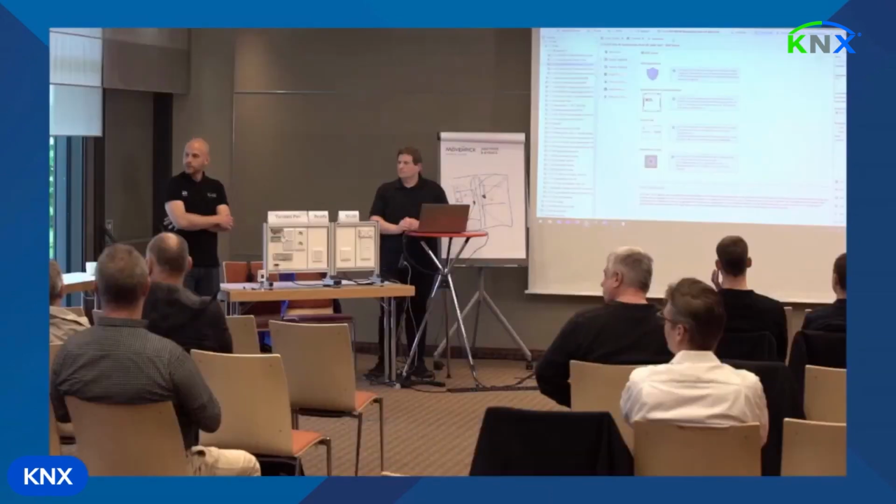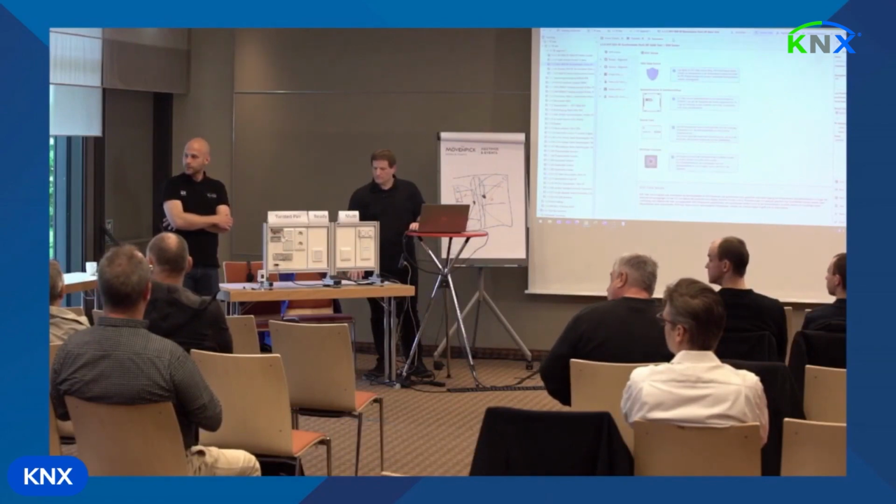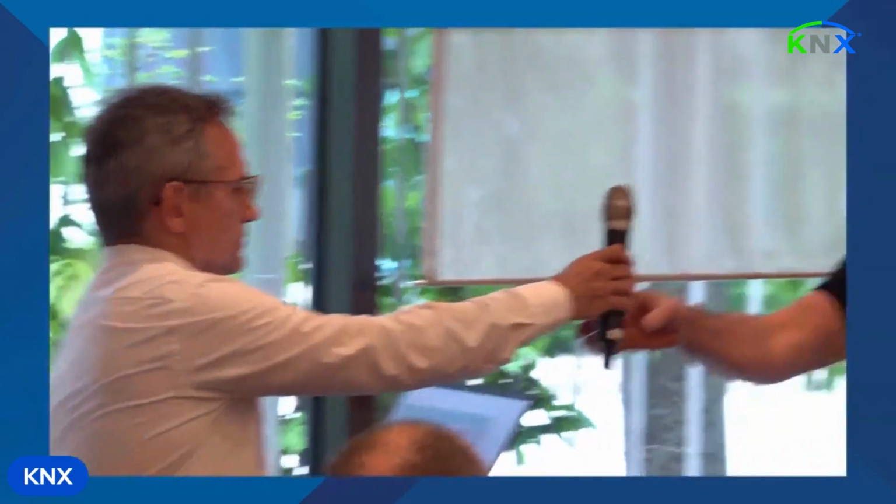Thank you. So now a question to Joost. Joost, you mentioned KNX IoT over Thread. So there is a question: is there a library available to develop a gateway or bridge to integrate a KNX TP installation with KNX over Thread devices? Yeah, for the time being, there is a KNX IoT open stack available, but only for end devices. There is not yet, as part of this open source stack, a corresponding open stack for the router functionality. This might come later, but for the time being, we concentrate on making the specifications. And for the end devices, there is an open stack which is already available via GitLab.